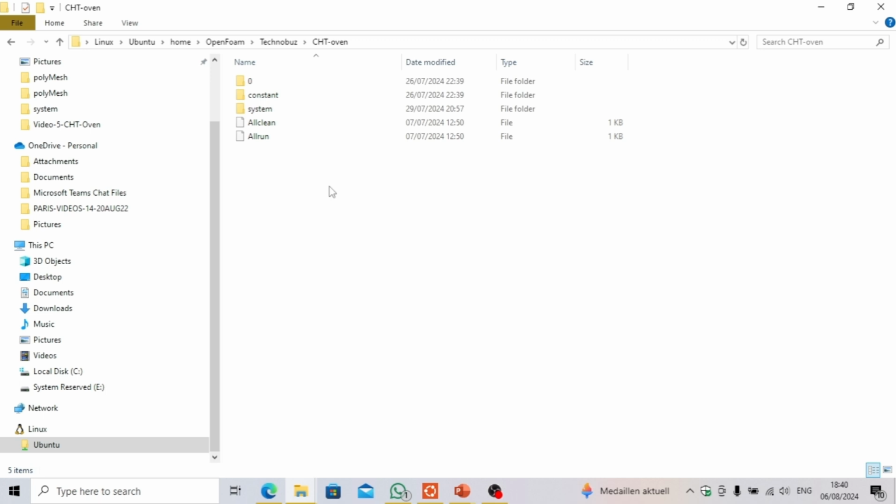Further, sometimes, though the mesh is created successfully, due to minor manual errors such as copy paste mistakes, STL file name mismatch, etc., the correct boundary faces are not identified. Hence, in that scenario, OpenFOAM will group all the boundary faces as one group and save. So it is very important to check all the boundary faces with respect to our case and update them. So let us check this first.